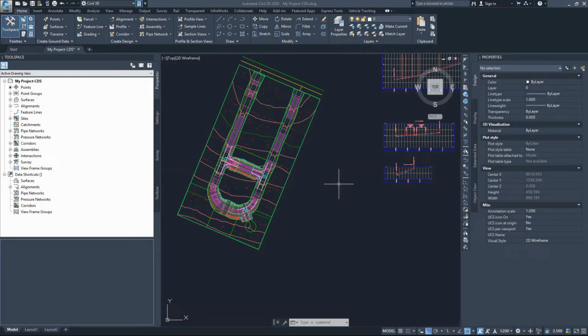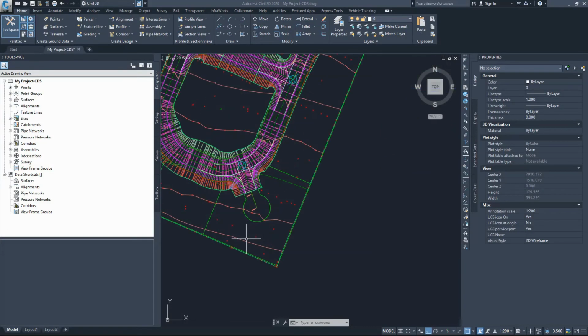Hi everyone, this is a video just to help you with your project in regards to designing the closed end road around here, what we called TAFE court. Simply, this is a closed end road here, so for the cars to go in, the allotments would be designed around this area. We make it a round end at the end here to give enough space for cars to do a U-turn and come out. These types of closed end roads, we call them Cul De Sac end or Cul De Sac road.